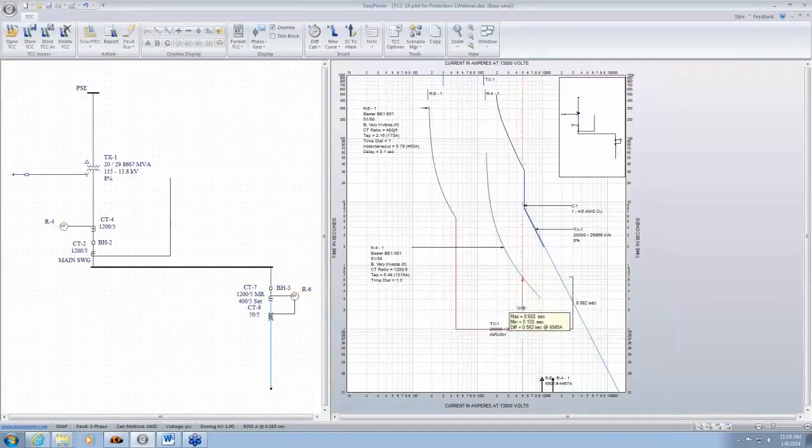Now, as you slide this along, you'll see the seconds, the time difference, increases. Whenever we place the time difference calculator here, we put it at the minimum time difference. So if you drag it left and right and want to bring it to the minimum, just take the cursor over the red arrow and double click on it, and it takes you automatically to the minimum point. You'll see that the minimum is 0.21 second.